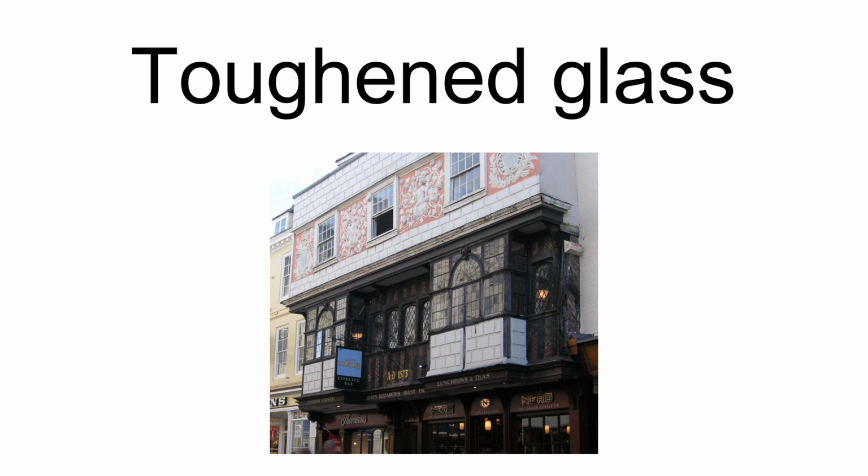The cut glass panels are put into a toughening furnace. Here the glass panels are heated to upward of 600 degrees Celsius and then the surfaces are cooled rapidly with cold air. This produces tensile stresses on the surface of the glass with the warmer internal glass particles. As the top thickness of the glass cools, it contracts and forces the corresponding glass elements to contract to introduce stresses into the glass panel and increasing strength.